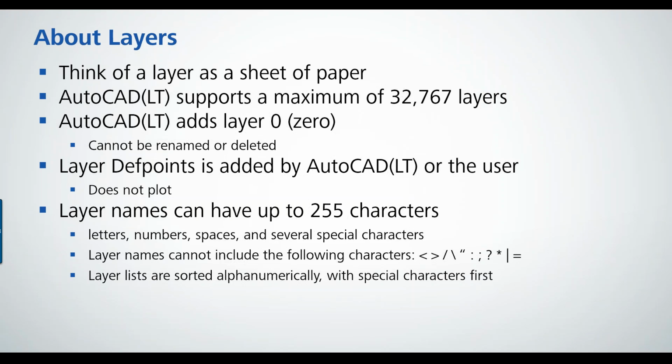I would also keep the layer names shorter than 255 characters. The reason is, if you are working with XREFs, keep in mind that an XREF, when attached to your host drawing, will add not only that external reference file's name, but also the layer name within that file into your layer dialog.